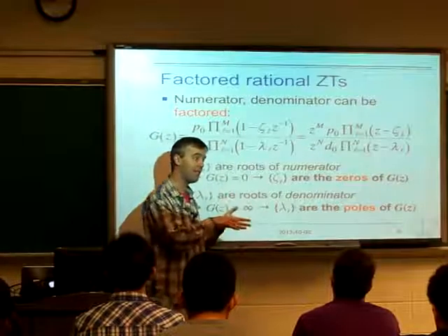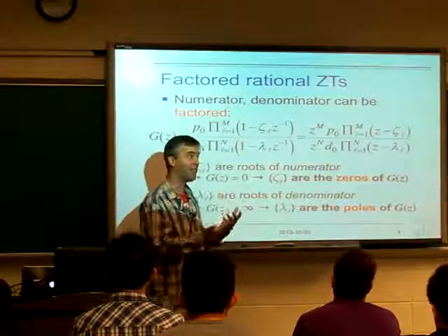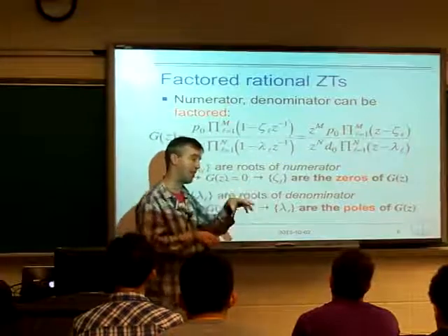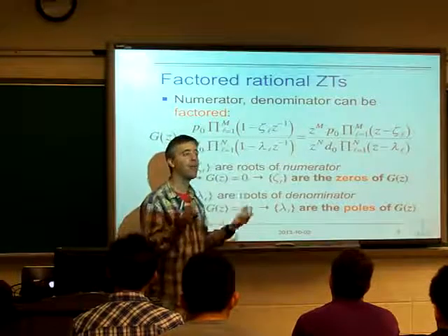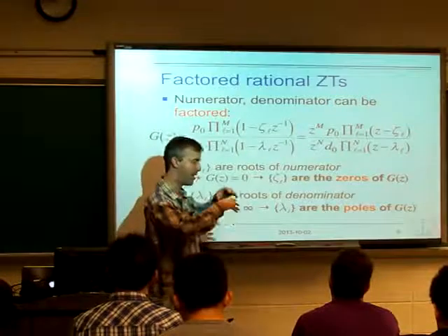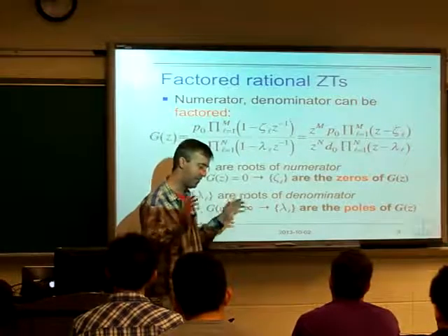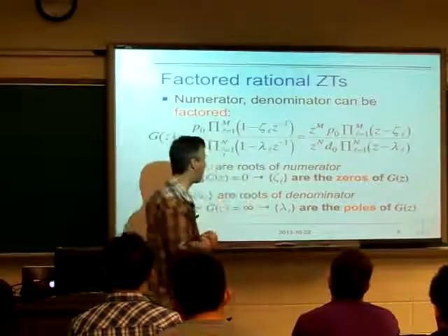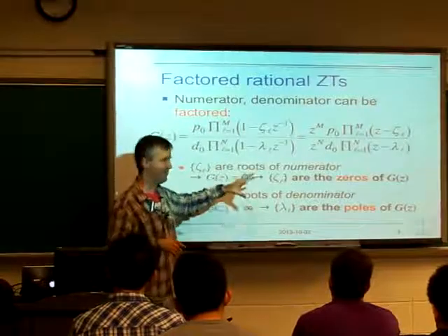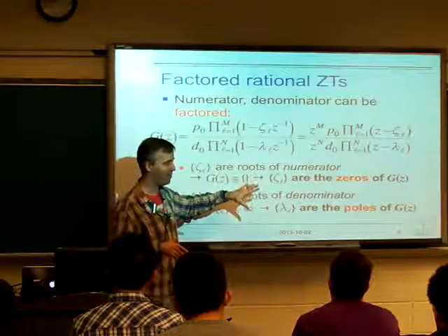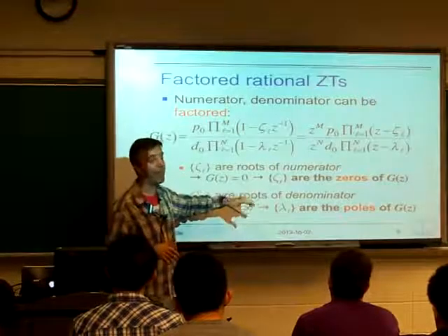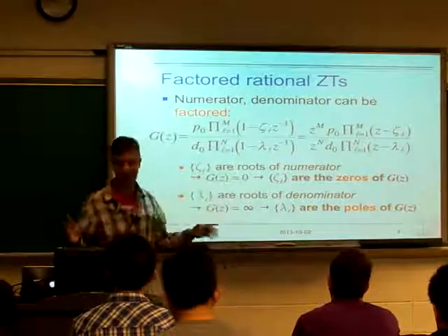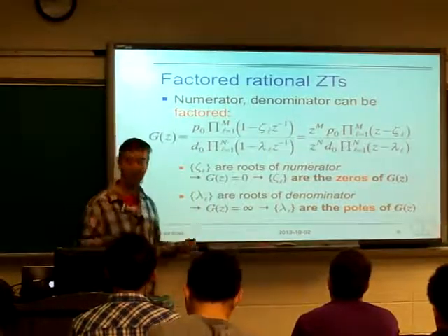It may be that the poles and zeros aren't in the region of convergence, aren't actually values of Z where this closed form expression matches our Z transform, but they still determine its behavior, right? Now all we care about is the overall shape of this closed form expression, which is determined by all the poles and zeros, even if they're not in its immediate vicinity. And so this is how we end up forgetting about the region of convergence, because now we're just interested in this closed form expression, and it's easier to think about those over their entire surface.